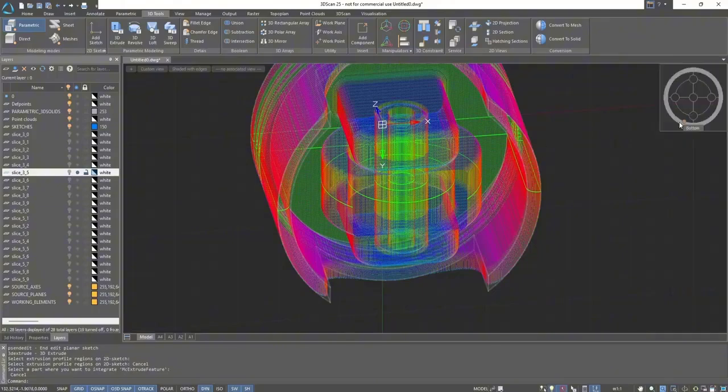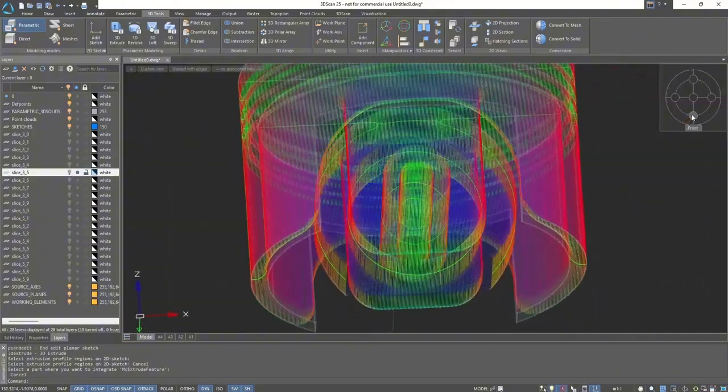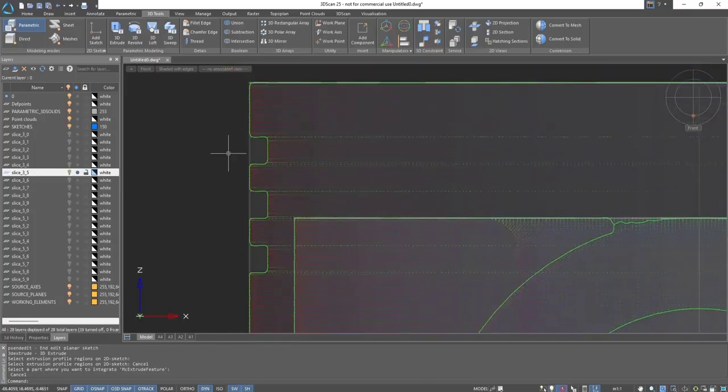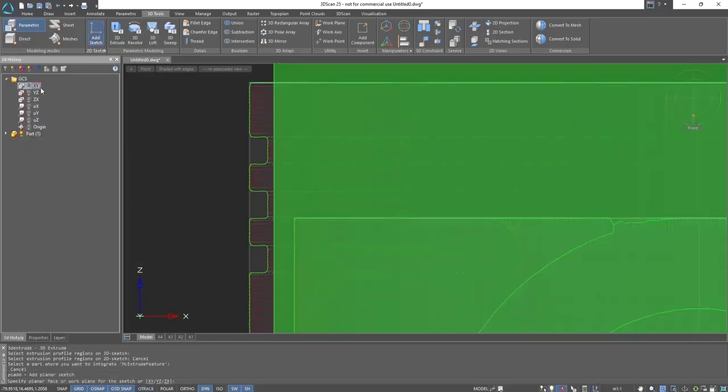Now you need to create grooves for oil removing and piston rings. To do this, we will include the middle section that we created in the first case. We will create only the uppermost groove, since they are all the same, and it will be possible to use the array function to create the other two. Let's add a new sketch to the drawing.